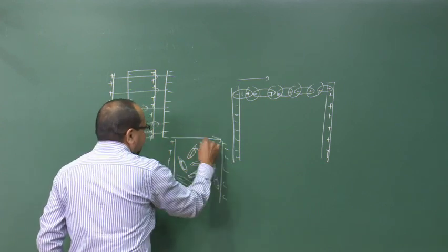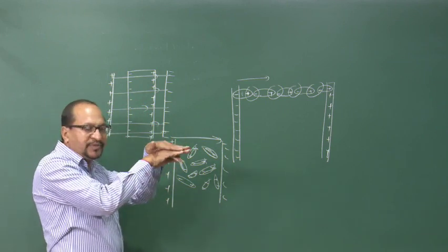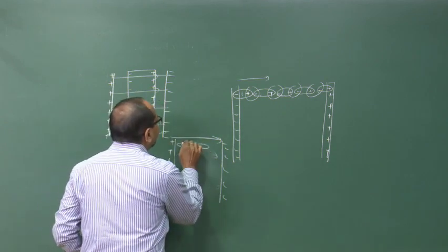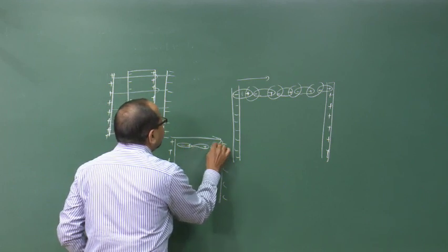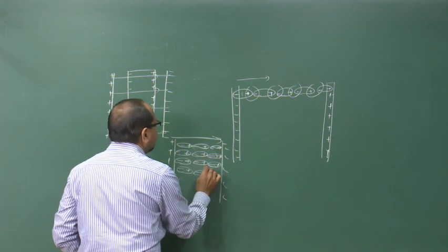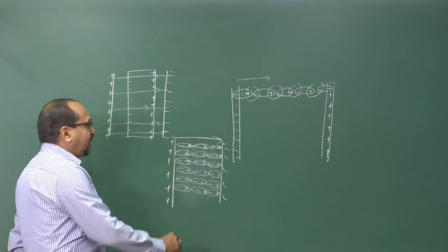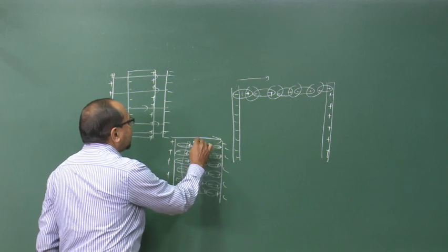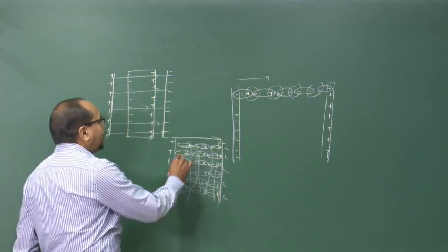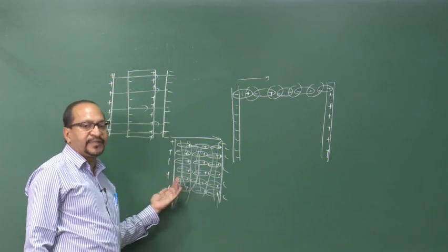But when we apply an electric field to this dielectric material, because of the electric field these polar molecules rotate and tend to line up in the field direction. So, again the result is the same. These dipoles get oriented in the field direction. Again the adjacent atoms inside the substance cancel the positive and negative charges, but there is uncancelled positive charge at one end of the surface and negative charge at the other end of the surface. So, that creates electric polarization.